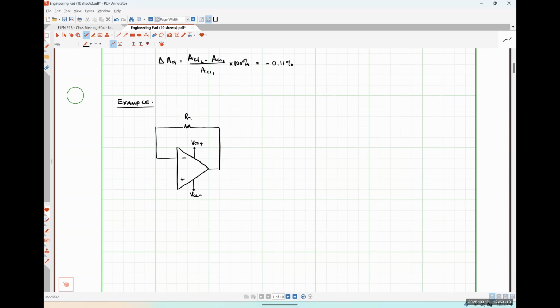I'm going to call this resistor R2. I'm going to place a resistor R1 between ground and my inverting input node, and I'm going to choose to apply my input signal here. This will be Vin, just so that I have a fully defined system, so to speak. I'm also going to choose to include some arbitrary load resistance here, RL, and this will be our output voltage.